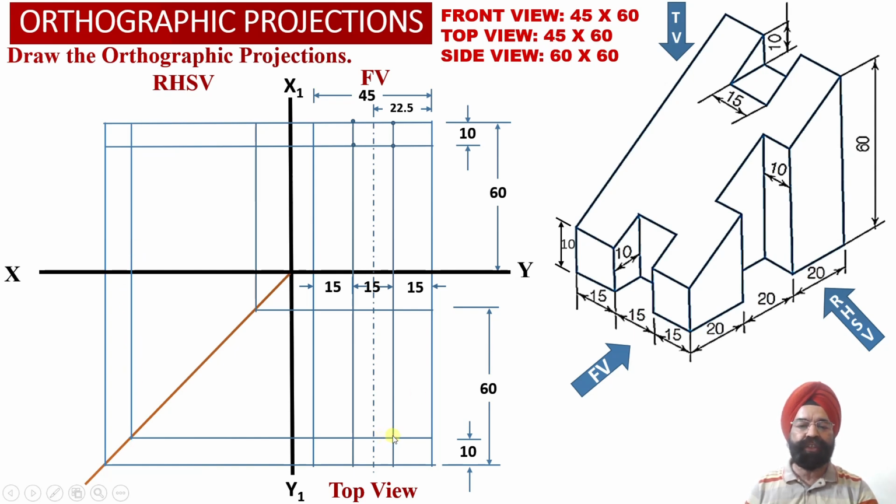So the moment we draw this horizontal projector line, we can check, as we look from the top, this horizontal surface at the base is a rectangular surface, parallel to the horizontal plane. Since the surface happens to be parallel to the horizontal plane, we are going to obtain true shape projections corresponding to this slot into the top view projections over here. So 4 dots into the top view projections we have obtained corresponding to the true shape projection of this particular rectangular slot onto the horizontal plane in the top view projection.